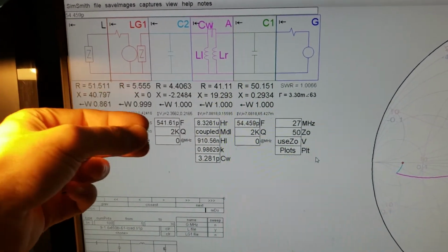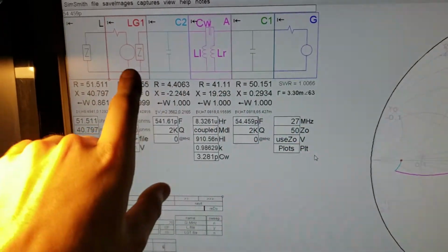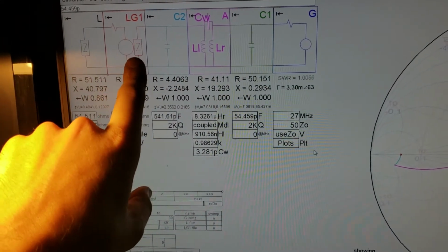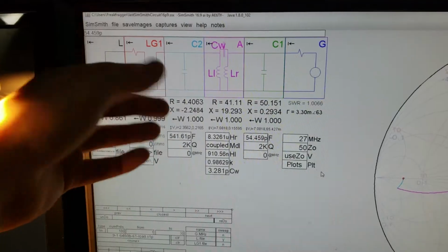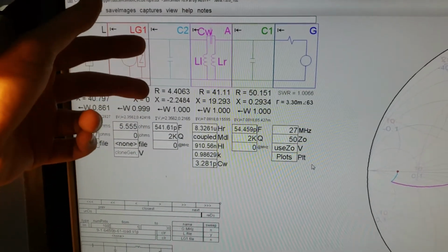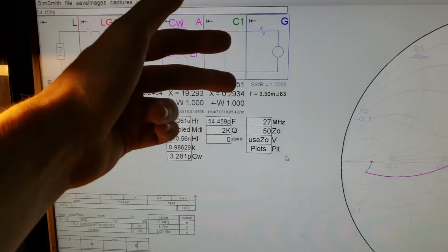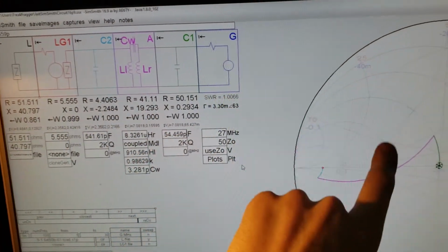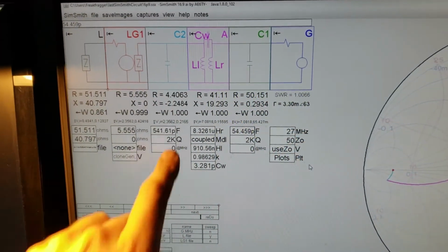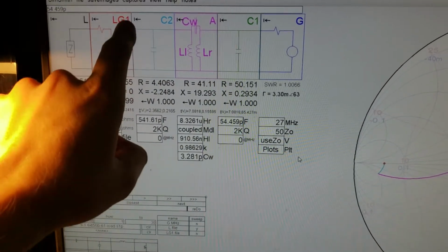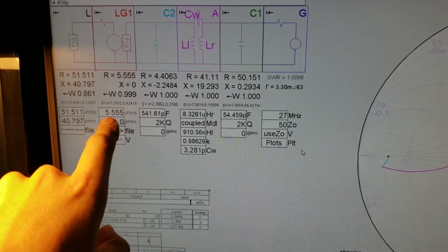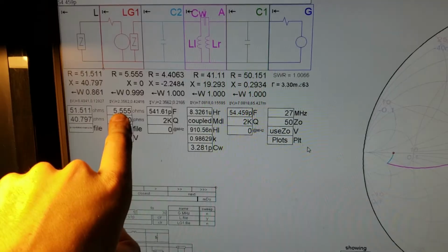And the reason I like to do that is because I don't have to simulate the transistors with a resistor. So when I measure from this point, I pull the transistors out of the amplifier, and I measure through the transformer and over into a perfect 50 ohm dummy load. And then I use the measurements on this side to get my impedance close to where my transistor needs to be.